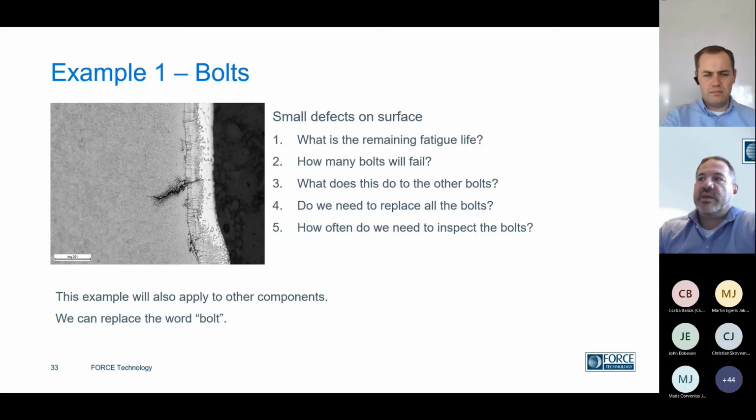So what you can see there is that from a fatigue testing program, we can answer a lot of questions. That's not just about the material itself, but it also helps to make decisions about when we need to do the testing, whether we need to have repair campaigns, what we need to order, and what sort of risk is involved.